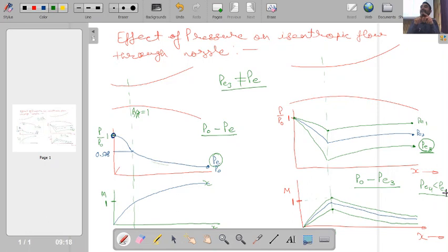I will find that I do not have any further change in the mass flow rate, and ultimately I am able to achieve this curve, the same curve for Mach number. So at the throat I am only able to reach Mach number equal to 1. Why? Because from our very initial area velocity relation, which I derived, dA by A equals M squared minus 1 into dV by V. From that relation, it is mathematically constrained that the area of the variable cross section will be minimum corresponding to Mach number equal to 1 only. So this is a physical constraint we have.